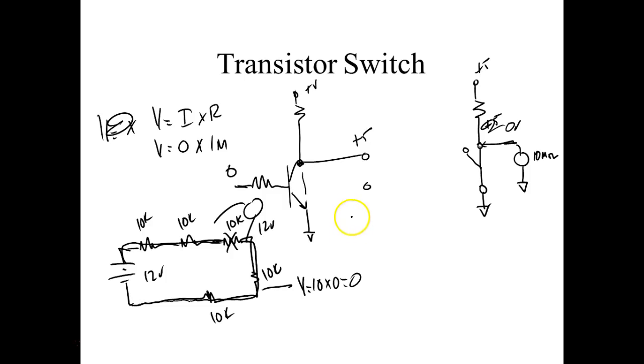What is this guy doing? Technically the circuit is called an inverter, but it's doing a logic we call a NOT. So the NOT logic has a name. The AND circuit is called an AND. An OR circuit is called an OR. On a NOT, the circuit is called an inverter. Now, why they did it, I don't know, but that's what it does. It inverts, right? A 1 in gives me a 0 out, a 0 in gives me a 1 out.